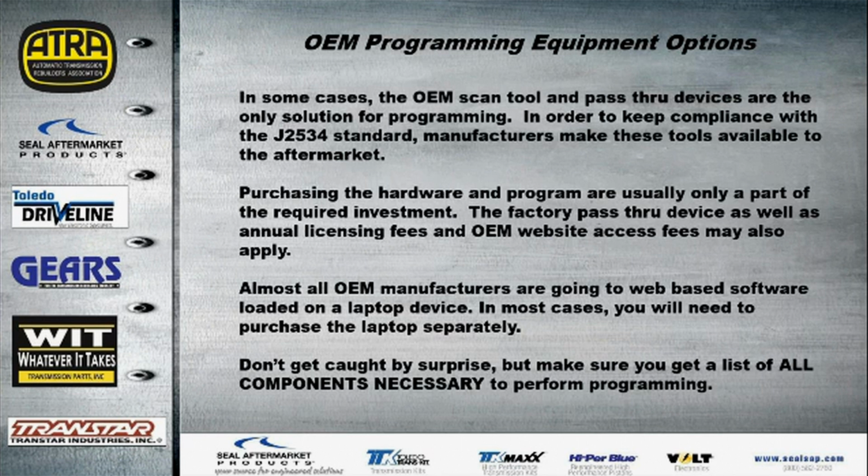In some cases, we're going to have to use an OEM scan tool. There's just no other option to actually perform this J2534 pass-through programming. And by the J2534 standard, basically the manufacturers at the very least have to allow us to purchase and access their scan tool to provide this aftermarket programming availability. So again, it's about compliance, not desire. So these tools are available for purchase.